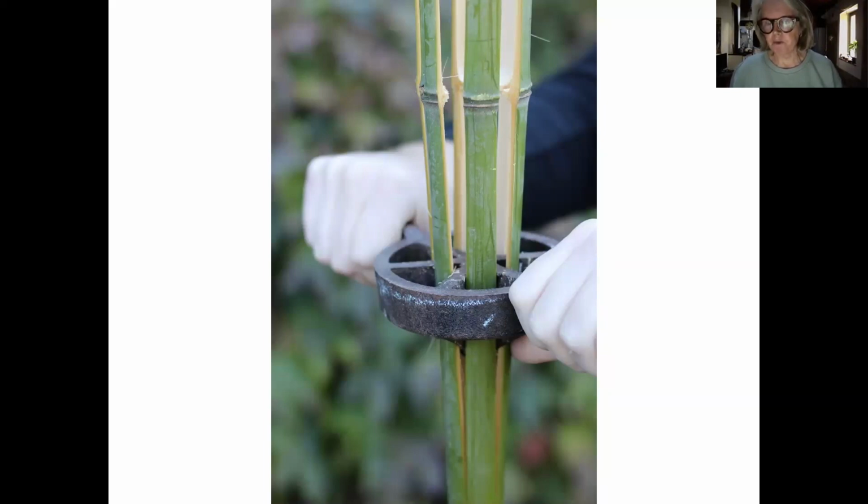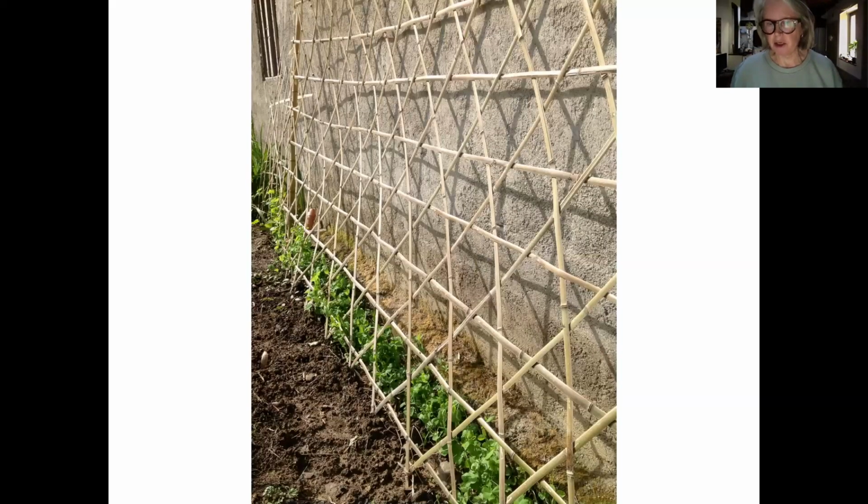which are very flexible. The green bamboo is very soft and supple, and so it's a good weaving material. And the style of weaving here is the three-direction, the triaxial type of weaving. Because it has triangles and hexagons in the weave, the friction between the elements of the weave makes it very stable, and a panel like this would take 3 or 4 canes of bamboo. So a small amount of material, you're getting a reasonable result, lightweight and fairly fast to produce.